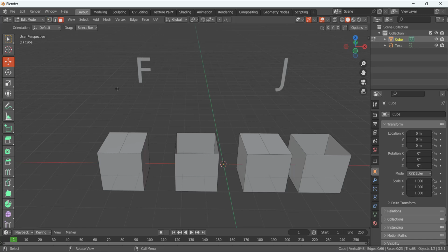So now if I go to the face selection mode, I select the top face, and you can see it's completely selecting this face. That means this fill tool did not cut through this face. And if I select this one, now you can see I am selecting these two faces here. So the join here cut this face. Okay, and again select these two and press F, and you can see it's connected these two by adding an edge between them. And if I press 3 to go to the face selection, now you can see I'm selecting this complete face. Now go to the vertex selection mode, and if I select these two, so what was the definition of joining? It will basically cut the existing mesh like the face or the edge.